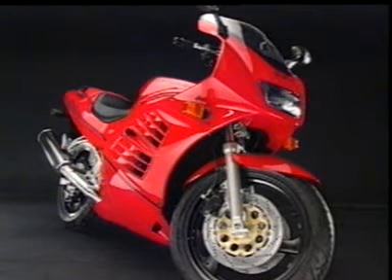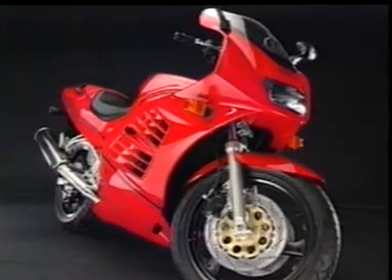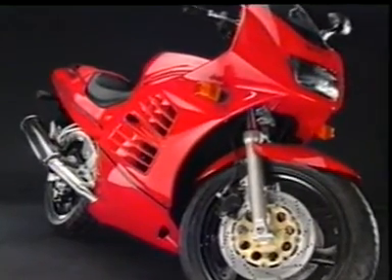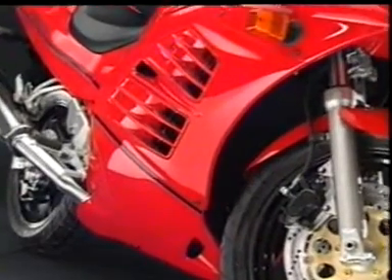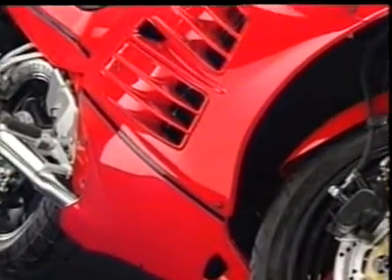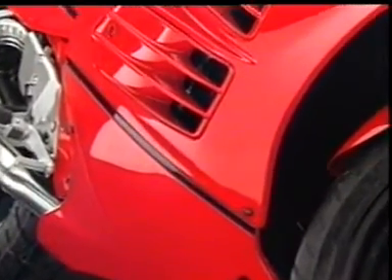When engines with larger exhaust capacity and larger power output are designed, instead of increasing the capacity of a single cylinder, increasing the number of cylinders results in better performance, less vibration, and a more comfortable ride. However, this also increases the number of parts, making maintenance more complex.